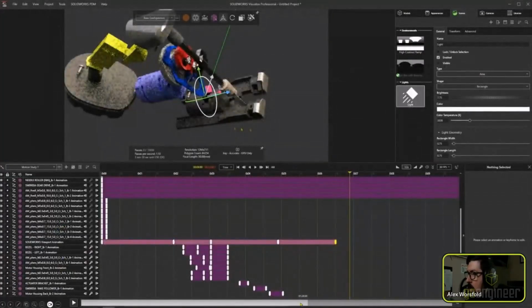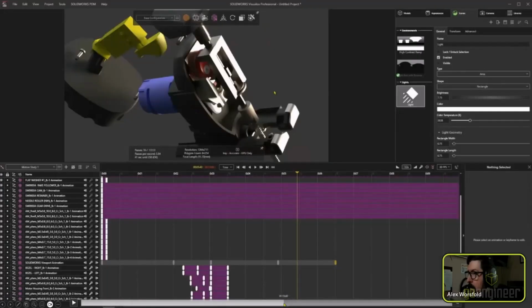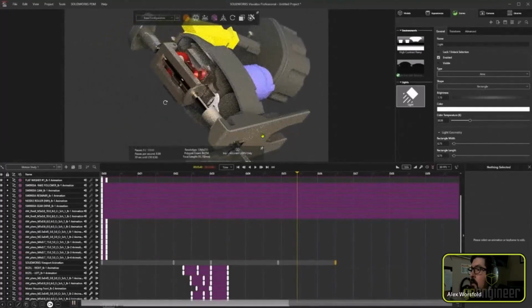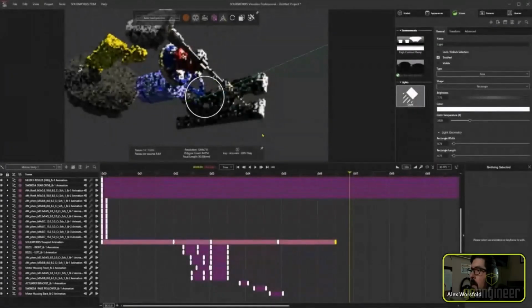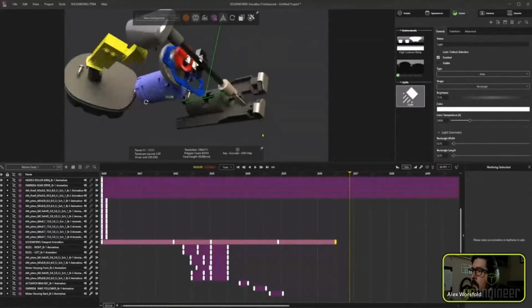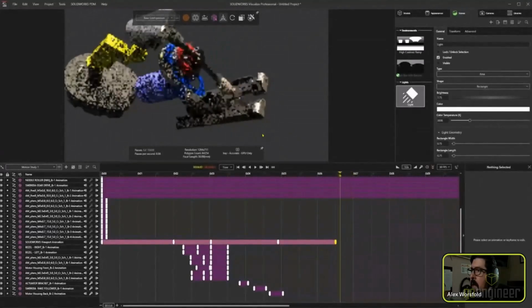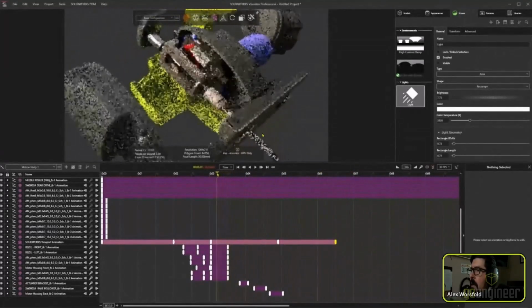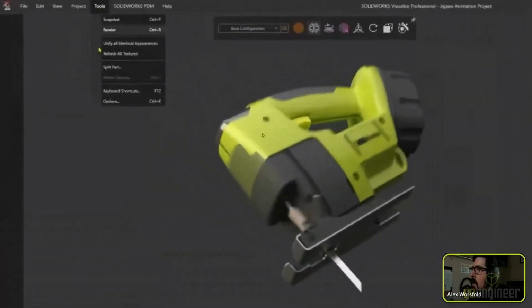Let's go back. So all I'm doing is clicking within the area of the model there, and it's going to illuminate that area. That looks pretty good, but I have full control over that light. Using the Move tool, I don't have to go through all the steps of adding another model and appearances and whatnot. I can just add that light directly into the Scenes tab.